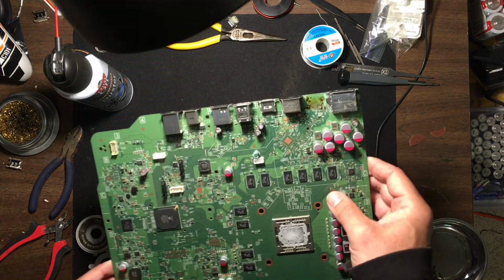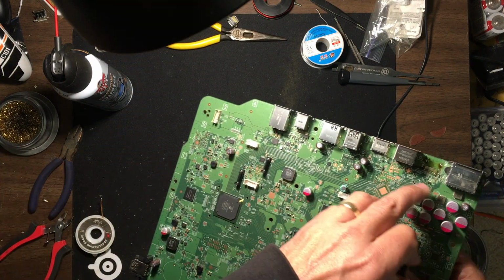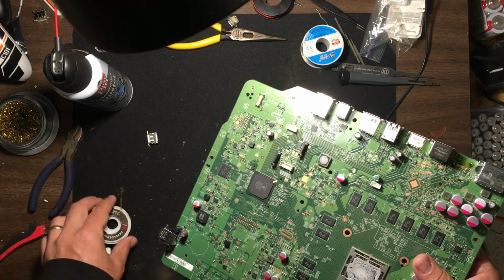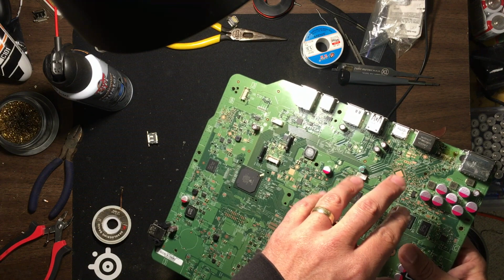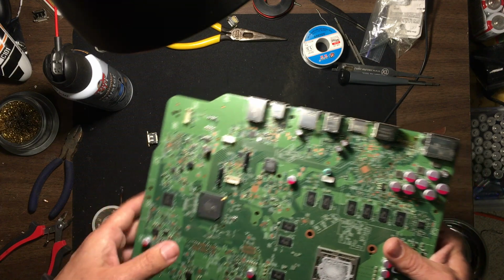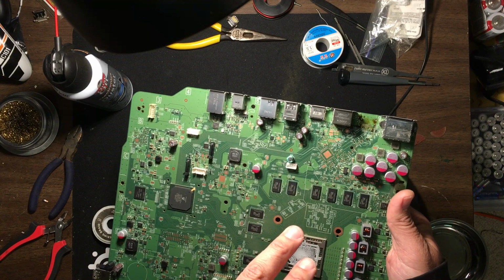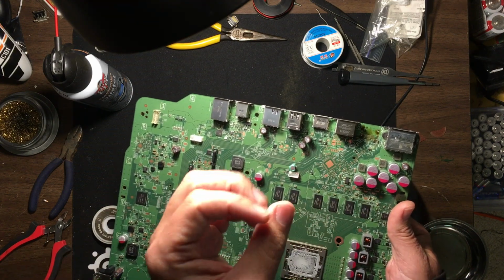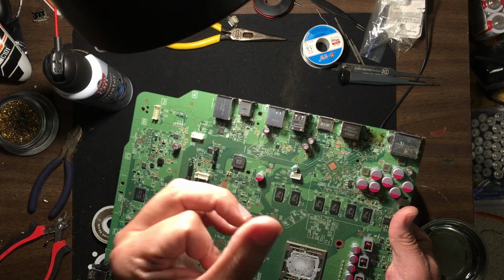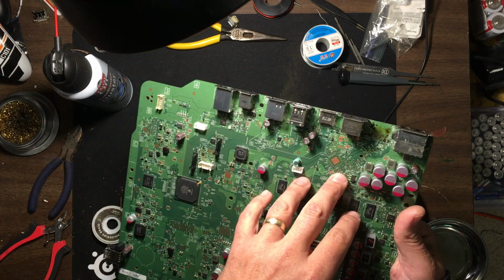So at this point, the hard part, as far as I'm concerned, is done. It's still going to be a pain in the butt to solder all those pins down and not have them bridged. Again, if they do bridge on you, the trick there is to not apply a lot of solder. Put a little solder on your soldering iron, have the soldering iron down on the pads, and then just independently do each one. You're still likely to have some bridging there. But again, that's a matter of using a lot of flux, which will help the solder stick to the surface that you want it to, and where you have the gaps, it'll basically separate from the gaps. So you're not going to want to use a lot of solder there.